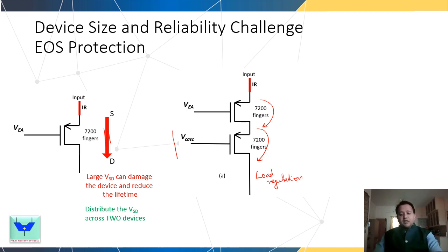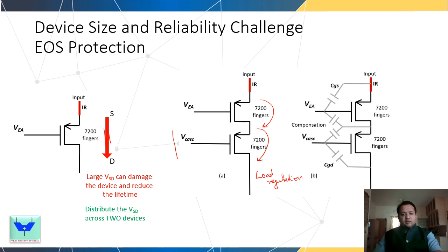Now, there is an impact that you would see because of this cascode. What is that? We will see an extra set of capacitance that is going to come. But the load capacitance would now be transferred to a CGD at this particular node from here. Without this device, this would be the initial place where the output node would be present. Now that output node is transferred to a lower place, where the output node is present here, and it is from here that the output is drawn.